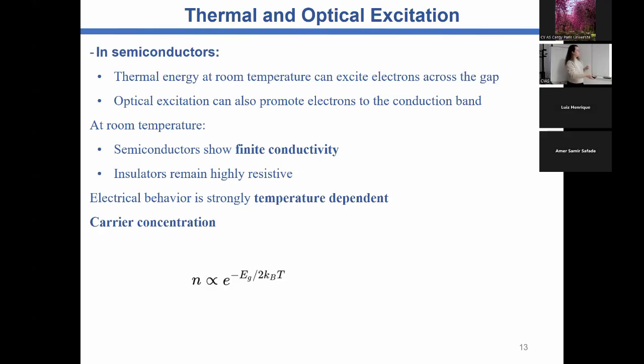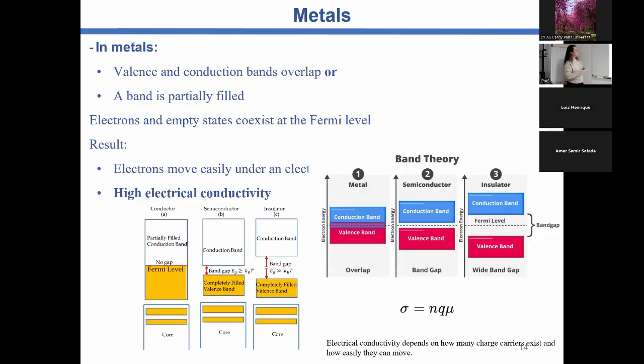As we talked, in metals the valence band and conduction band overlap, and the Fermi energy level lies in both bands, or they have just a small separation, so just a small quantity of energy can move the electron to the conduction band.